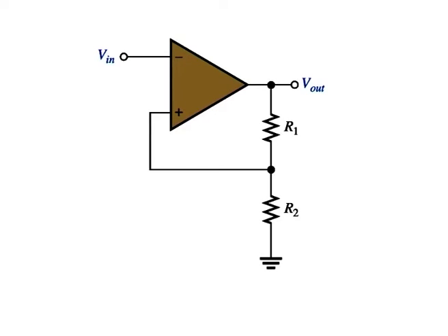This two level hysteresis is established with a positive feedback arrangement as shown in figure here. Notice that the non-inverting input is connected to a resistive voltage divider such that a portion of the output voltage is fed back to the input. The input signal is applied to the inverting input in this case. The basic operation of the comparator with hysteresis is illustrated in this figure.